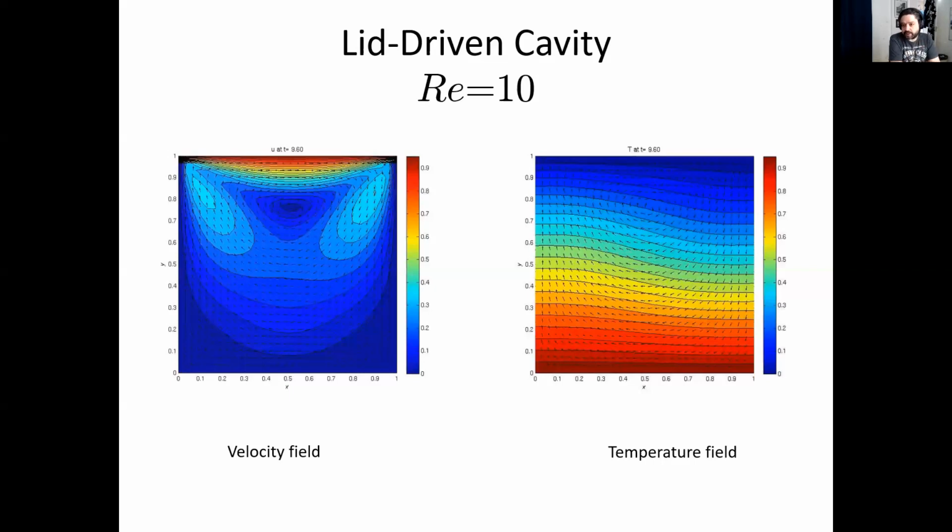As you remember, this relates to the viscous time step limit, which reduces your time step considerably. That is a problem one has for low Reynolds number flows if we treat them with the explicit time stepping that we have in our code.